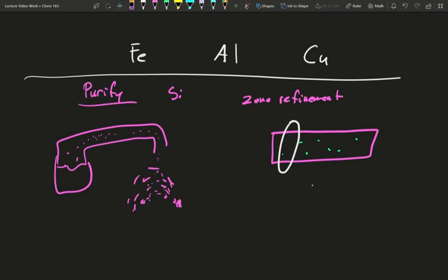Well, the particles inside can now freely move, and they'll bounce around. There's not a lot. And so as they move to a side over here, well, the back side now can refreeze. Without that impurity, it's colder than the freezing point. We're not quite heating it enough to melt the pure material, just slightly under it, so this will start to crystallize. If you grow your crystals slowly, impurities tend to flow out. They don't get trapped in the crystal forming. And so this will cause those impurities to move forward a little bit.